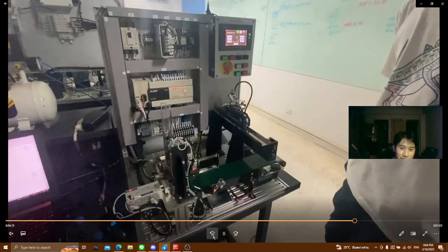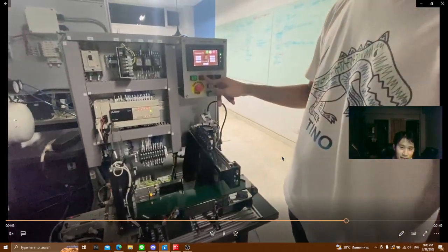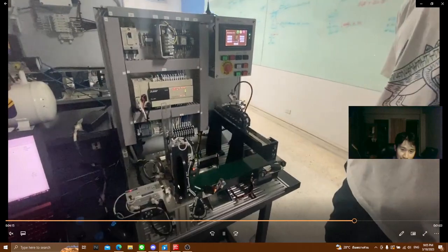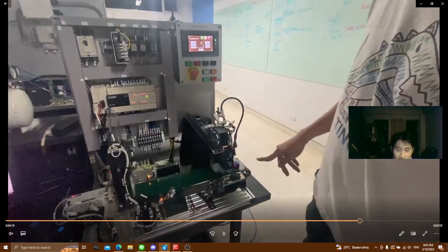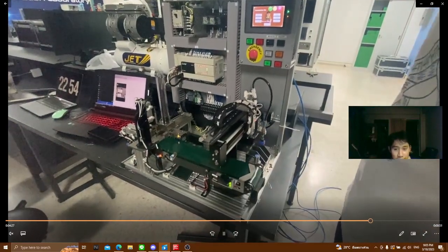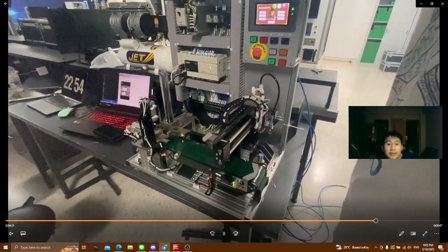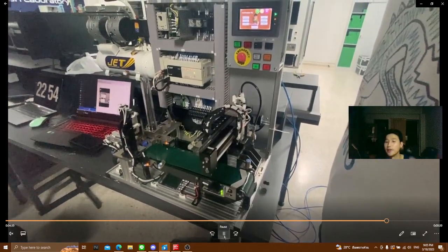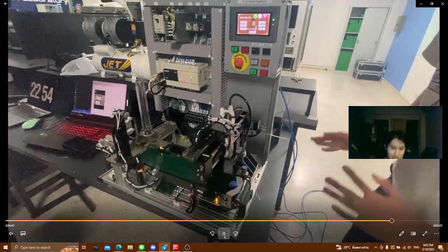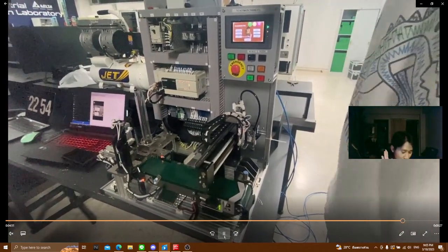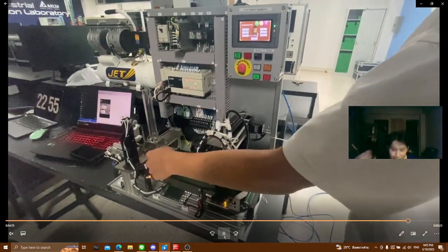And now let's take a look at how we start the work. We place the cycle stop and make sure by pressing the reset button and then click start. If you slide out right here and then push out, this one is the plain workpiece. Then you pull up, check, wait, and then throw it away. Sometimes in this robot we have a little bit of failure because the probe didn't hit hard enough for the metal workpiece, which can cause an error that detects it as a plain workpiece.